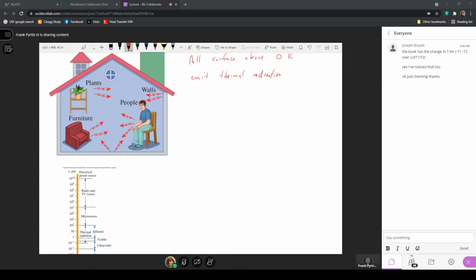The reason that you perceive the steering wheel to be hotter is that the heat flux from that vinyl when you touch it is much higher into your skin than the heat flux from the cloth seat to your hand. If you put a thermocouple on them or a thermometer right next to them, you will find that they are exactly the same temperature, but the heat fluxes are very different because of the thermal conductivities of the two materials, in that heat has to transfer from that material into the skin on your hand.